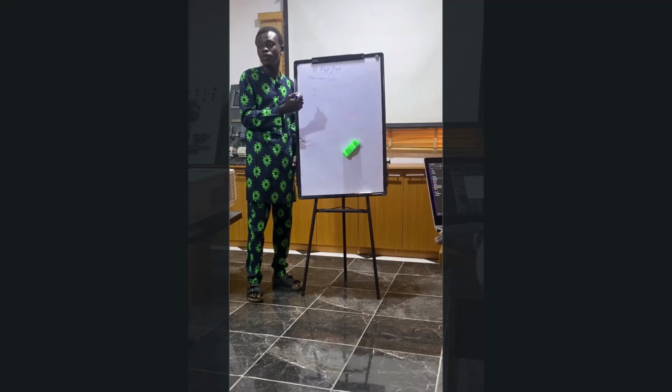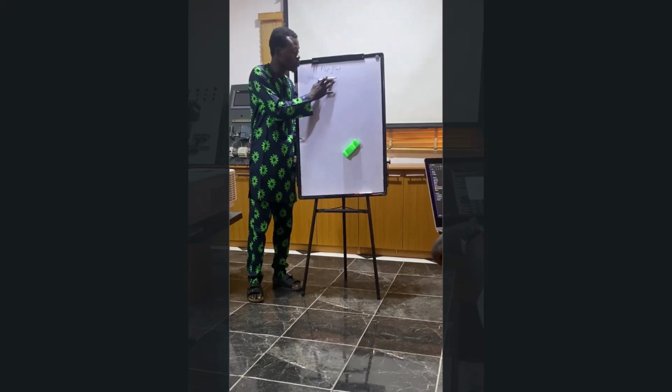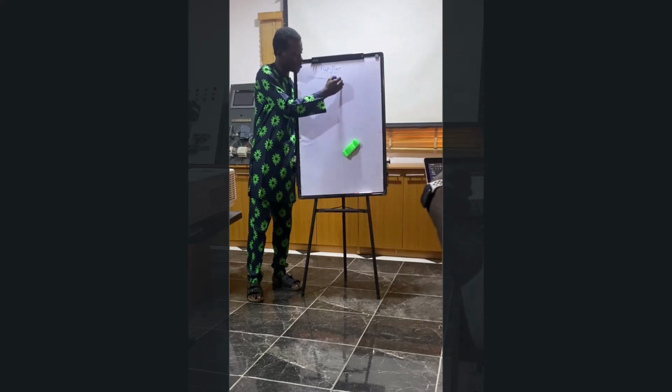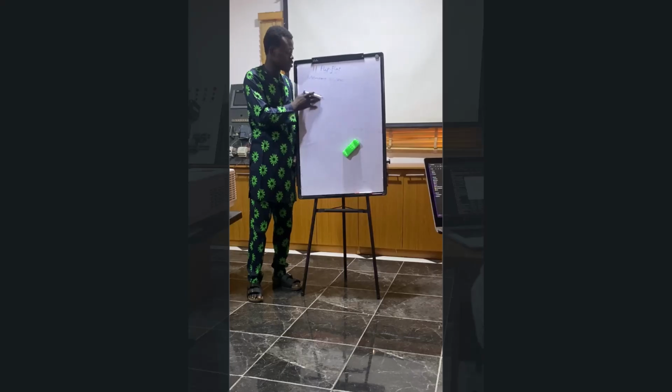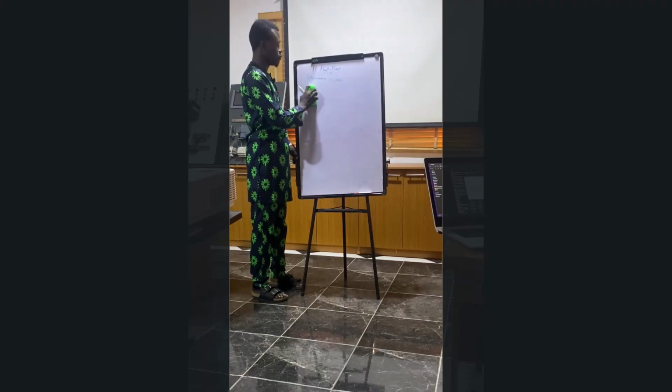Say you are writing, maybe let me just use the word, a complex program, where you want to have a placeholder for your signal or your variable. In Siemens there are two categories of memory you can use for that. You can use the memory addresses, and you can also use the data block. But for the purpose of this class, we are only going to be looking at the memory address.